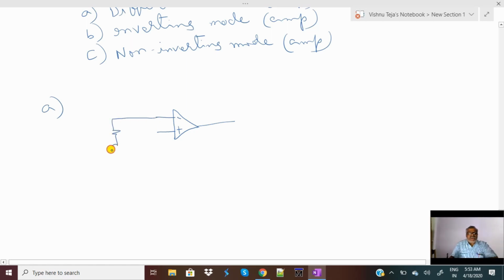One input signal at the inverting input, represented with Vin1, in series with its internal resistance R1, and another signal at the non-inverting input, represented with Vin2, in series with its internal resistance R2. They may be AC signals or DC signals, no problem.